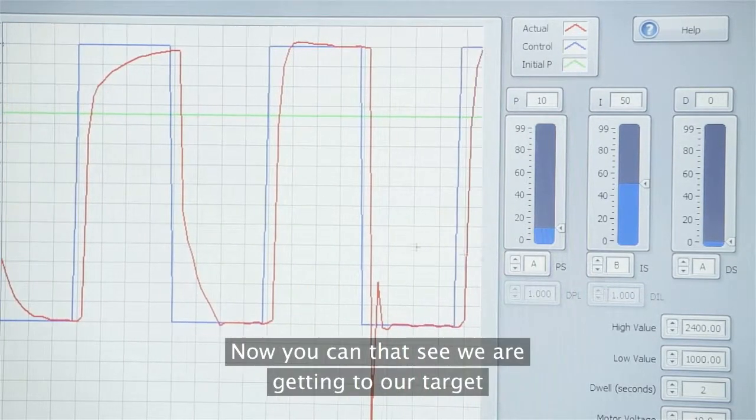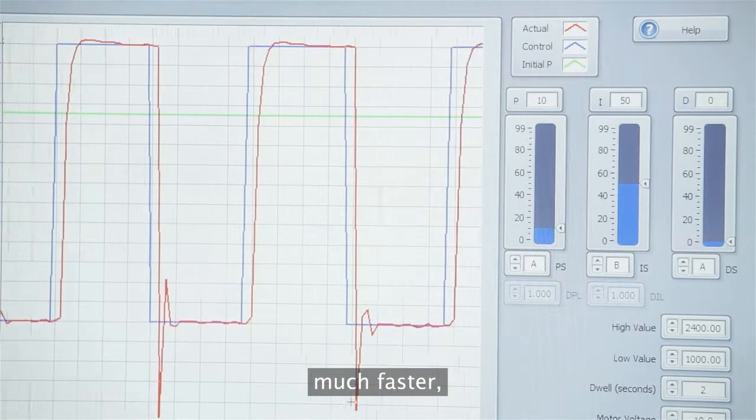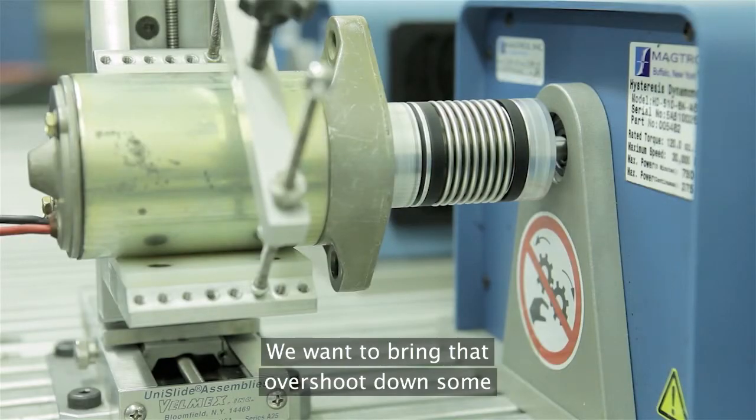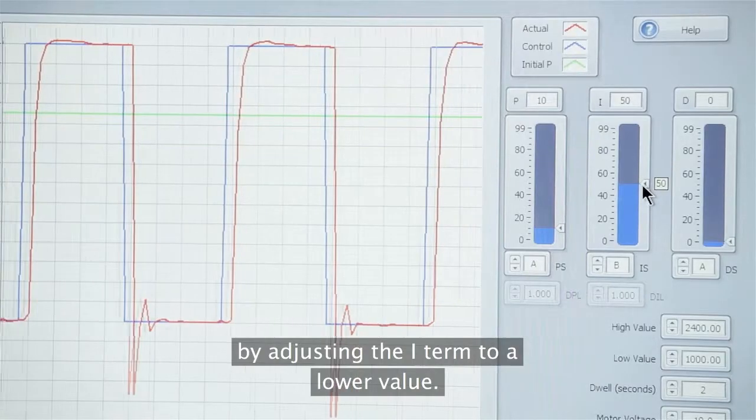Now you can see that we are getting to our target much faster, but we have a fairly large amount of overshoot. So we want to bring that overshoot down some by adjusting the I term to a lower value.